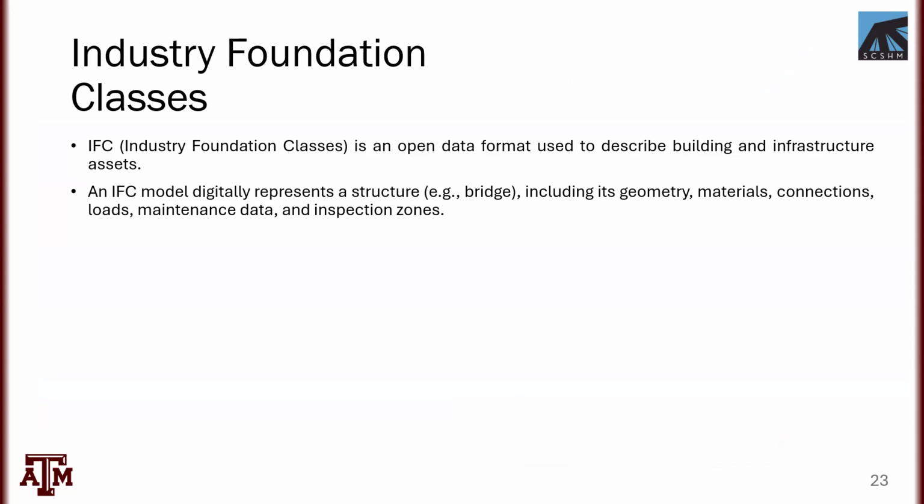Finally, I did mention IFC classes. I just want to talk a little bit more. So industry foundation classes are basically an open data format standard that's designed for a lot of various infrastructure assets out there: buildings, bridges, other assets. They are a way of representing digital assets, and they are interoperable. What that means is you can work with IFC models within different software classes or software types.